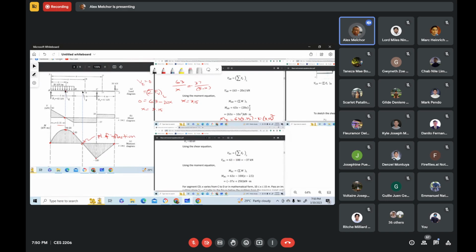Okay, inflection. This is the point where there is a change of the curvature of the beam. You see that from that point to that point there, the area here is positive area. So that means that this is positive moment. Okay, so that is from this point to this point. We project this point here with zero moment vertically upward, and we label that section as section F.